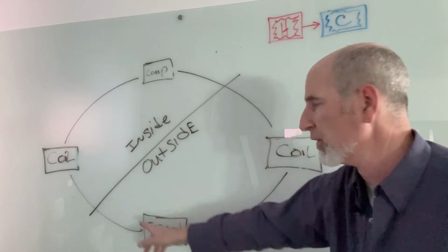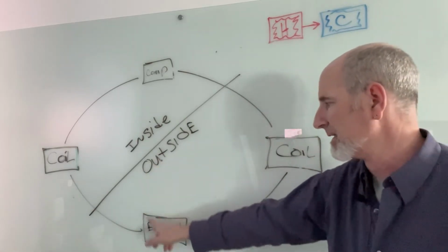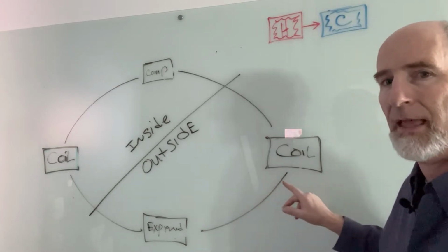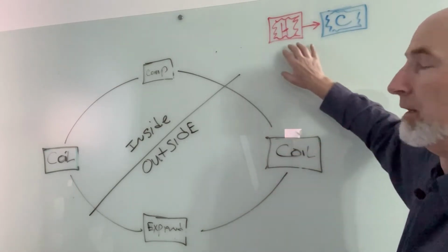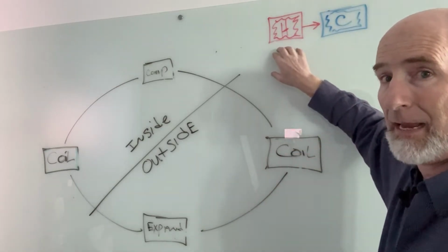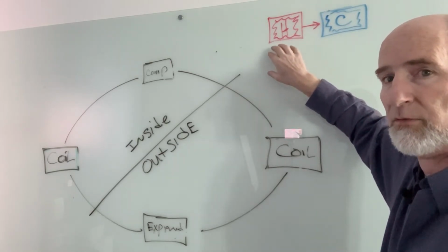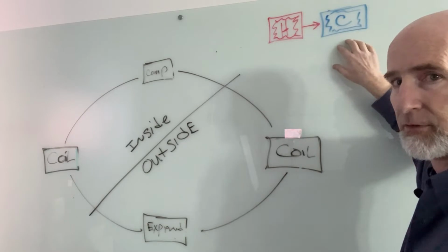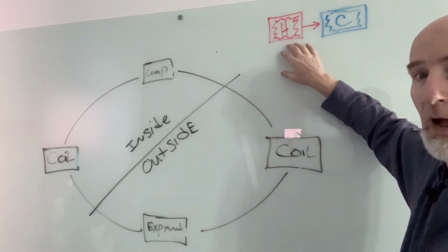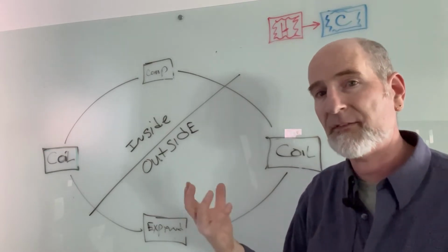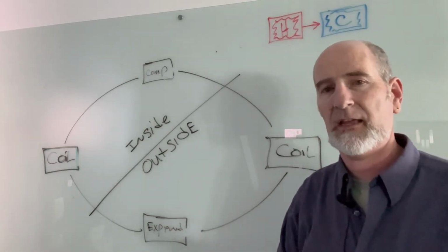So if I reverse this situation, I send it through the expansion valve and I cool that refrigerant to more than negative 10 below, the energy outside in that really cold air, but there's energy there, is going to move from higher concentrations to lower concentrations. In essence, from hot to cold, because negative 10 is hotter than negative 20.